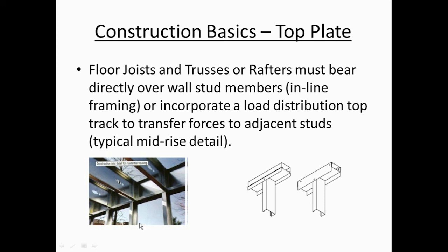So we like to see things line up vertically on top of each other. You'll notice this little guy right in here. I talked earlier about how the web comes into play with interaction shear and web buckling. That's a web stiffener that may have to be used to transfer the load. If we don't have the capability because of design to do the direct load path, there are these options where you can use load distribution to transfer load back to the framing member or the stud adequately.